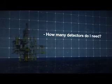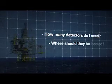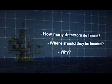Whether using the geographic or scenario-based method, fire and gas mapping provides unprecedented insight into the effectiveness of fire and gas detection systems. The use of mapping finally allows designers to answer the questions: how many detectors do I need? Where should they be located? And why? This results in more effective, more consistent, and more defensible designs.